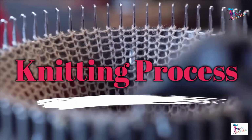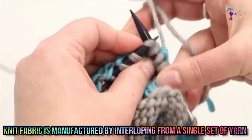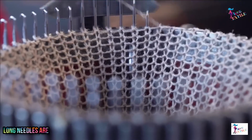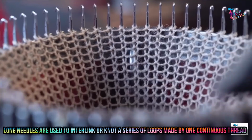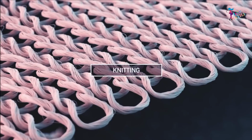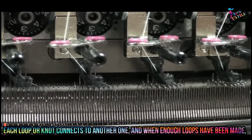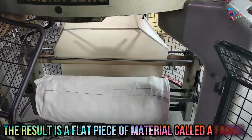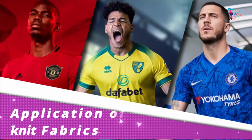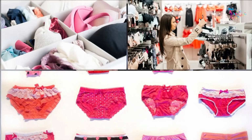Knitting process. Knit fabric is manufactured by interlooping from a single set of yarn. In knitting, long needles are used to interlink or knot a series of loops made by one continuous thread. Each loop or knot connects to another one, and when enough loops have been made, the result is a flat piece of material called a fabric. It is particularly a comfortable form of fabric structure for sports, casual wear, and also for undergarments.